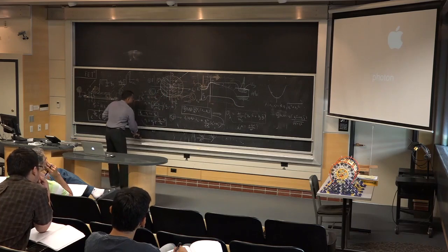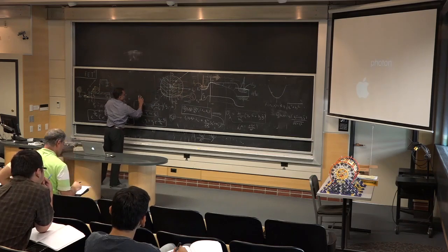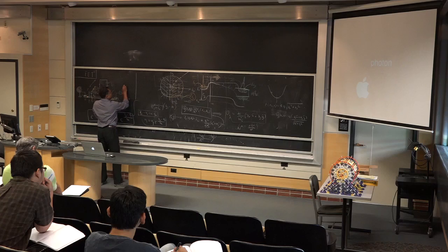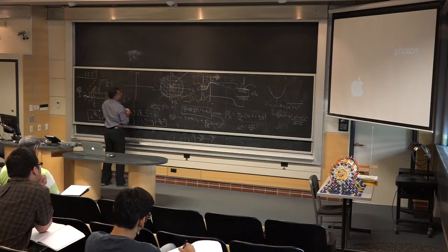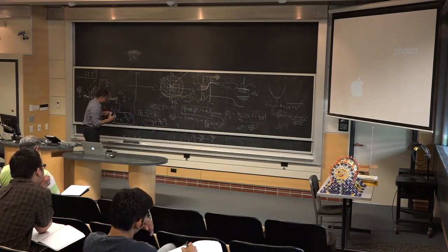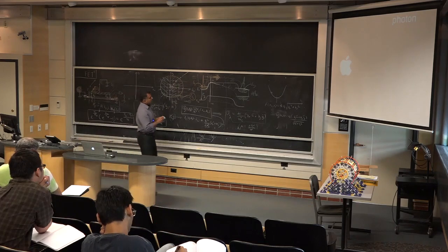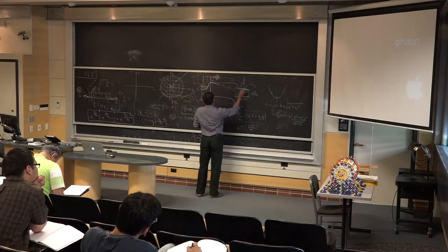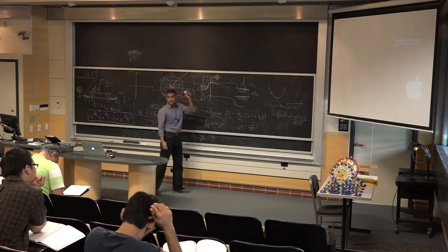Clearly, let me sketch this picture on the side now. Kx and Ky. And now I'm going to just draw circles and forget about the discreteness or the grid points. What we're saying is, because the drain quasi-Fermi level is so much lower, the amount of carriers going to the left has suddenly gone down exponentially.